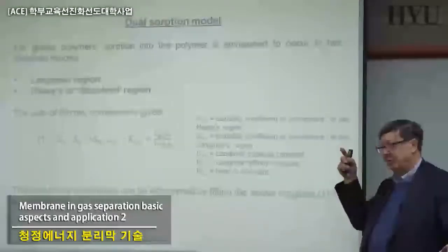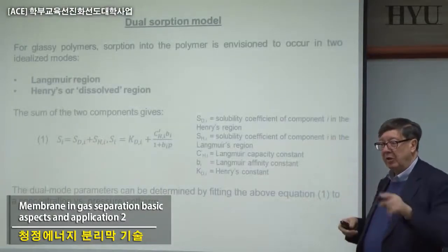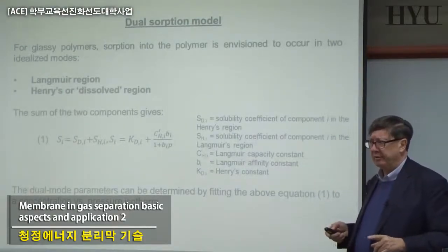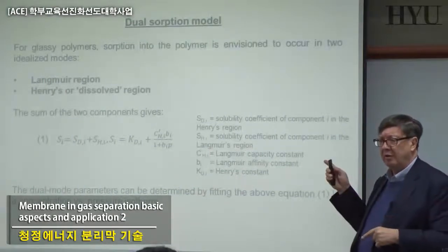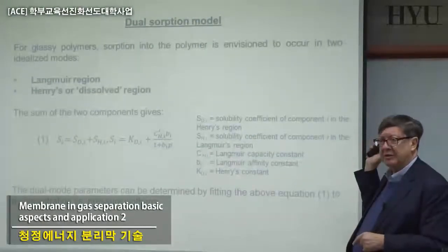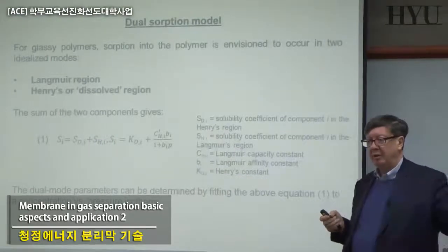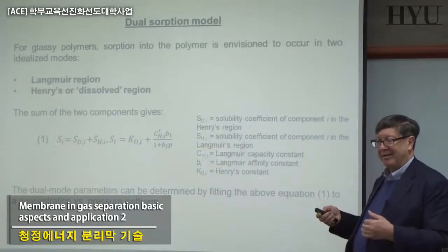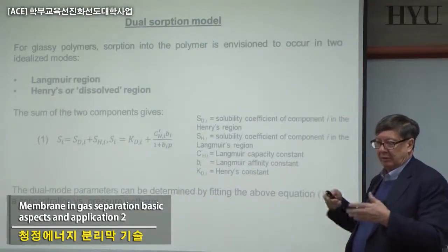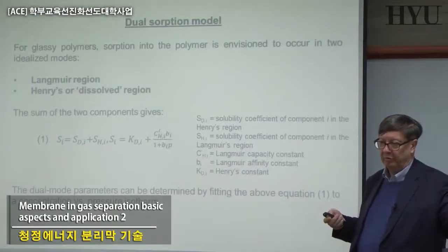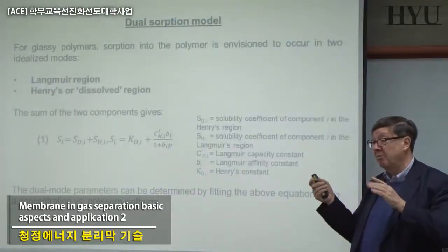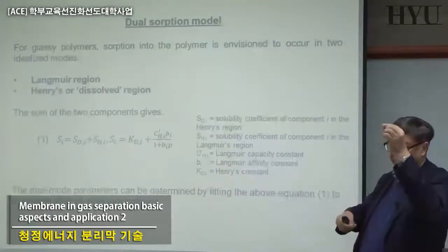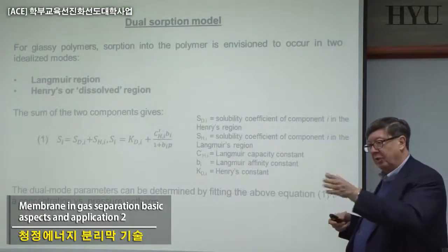Most of you don't know. We wrote the equation last time, and we said that the transmembrane flux is given by Fick's law. Basically, you have solubility, but the species entering the membrane diffuse across it under Fick's law. There is a driving force, a difference in pressure or concentration, and you just have a flux.